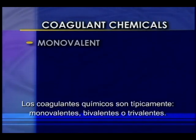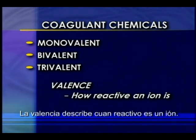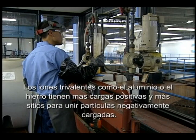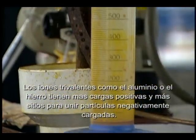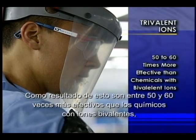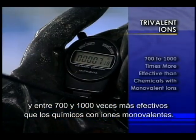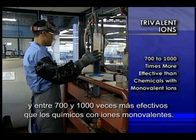Coagulant chemicals are typically monovalent, bivalent, or trivalent. Valence describes how reactive an ion is. Trivalent ions, such as aluminum or iron, have more positive charges and more sites to bind negatively to charged particles. As a result, they are 50 to 60 times more effective than chemicals with bivalent ions and 700 to 1,000 times more effective than chemicals with monovalent ions.